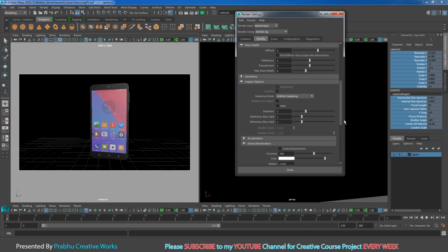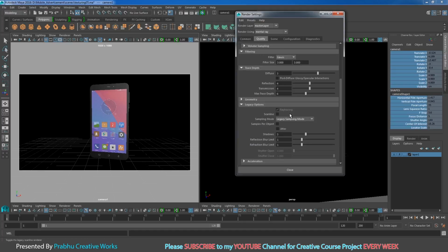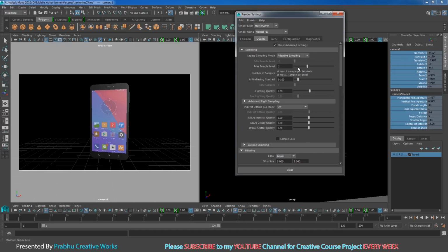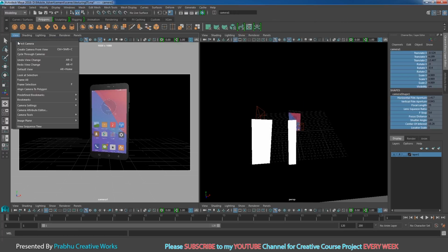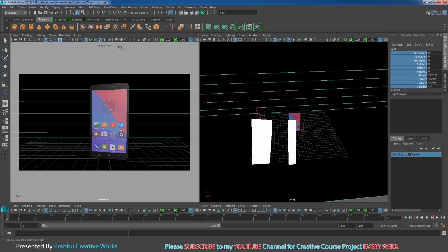You want to choose infinite sampling to legacy sampling mode. So go up. Here you need to choose maximum sample level to 2 and that's it. Now go to view, select cam. So you want to lock all the values for your camera, and then click this view and click render again.